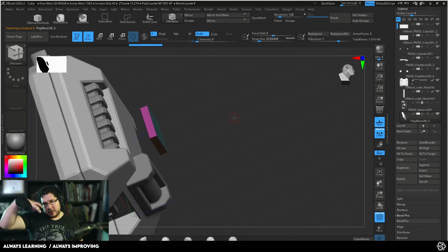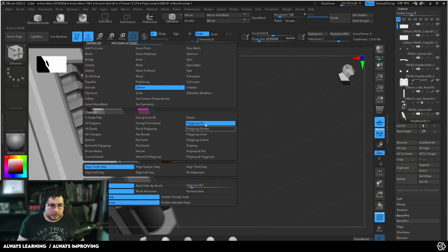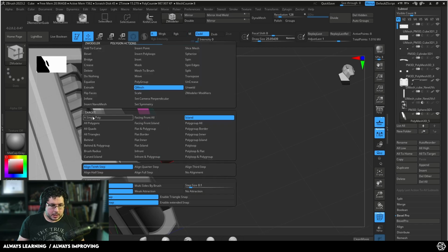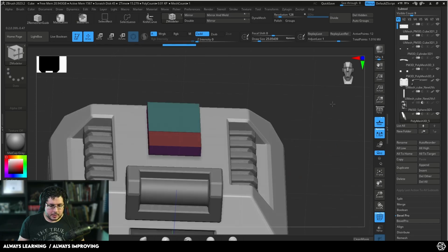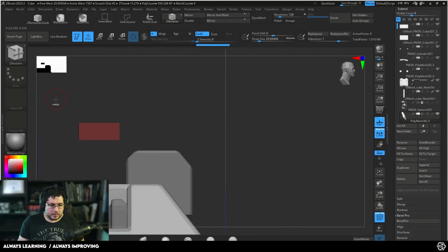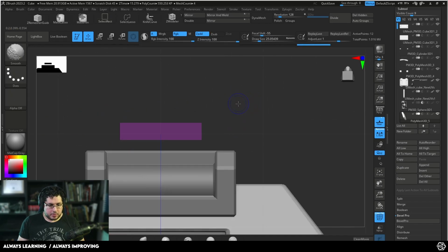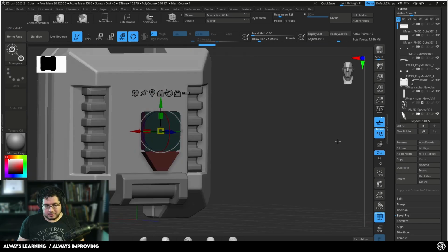And what I want to do is create a cross made out of 4 elements. So it's not going to be a full cross. I'm going to grab the bottom part of this face and I'm going to polygroup this little guy right here. Polygroup, let's say single poly. There we go. We're just going to drag this down, something like that. And then we can mask this poly like this. Control click, invert. And then with R, we can scale this in to generate this sort of shape.